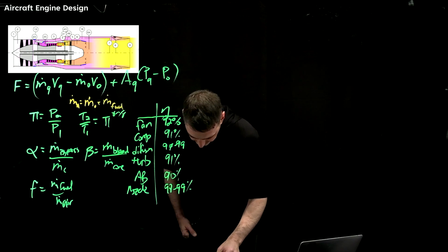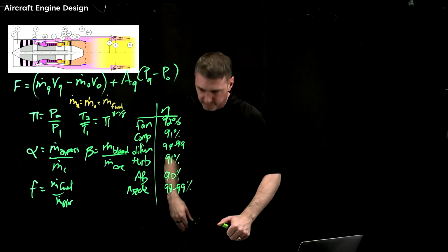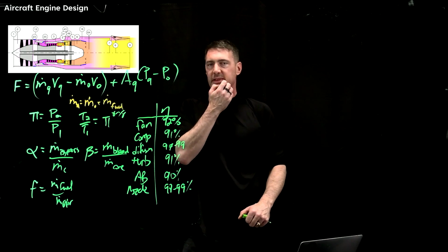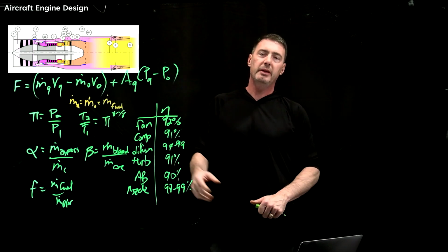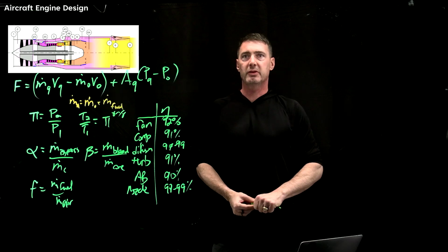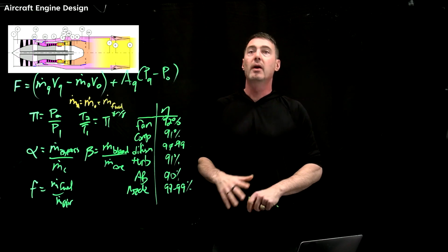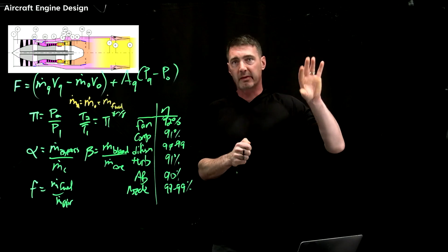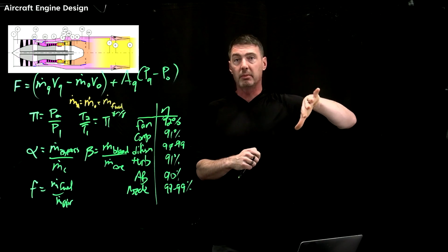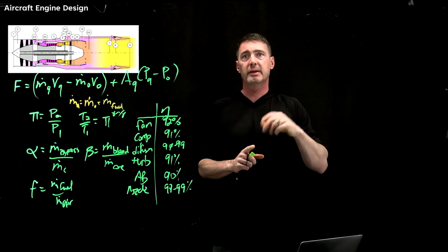Okay, so that gives you a rough idea of efficiencies. It all stacks up, so for sure don't just assume isentropic everywhere. When you're doing your engine balance, you would do all of this stuff. Oh, by the way, this book is also going to talk about the software available to run a lot of these things, so take a look at the software.